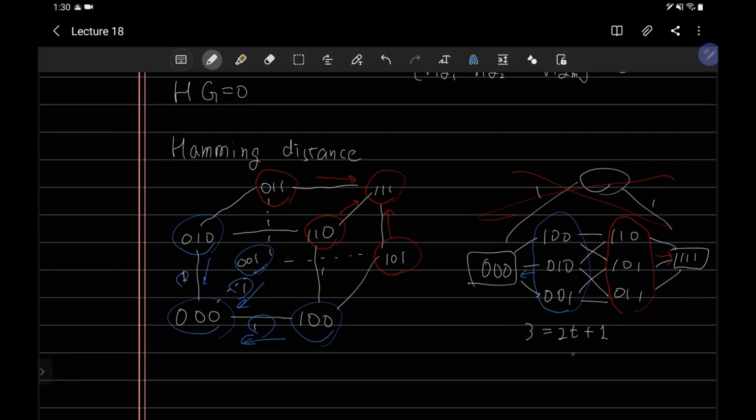What this implies is that we can always separate this code word space into two, or if we had more valid code words, then at least we can separate the entire space into sections or regions, and within each region there is no ambiguity when you receive some incorrect code word, and it will always be obvious which direction you should correct to.